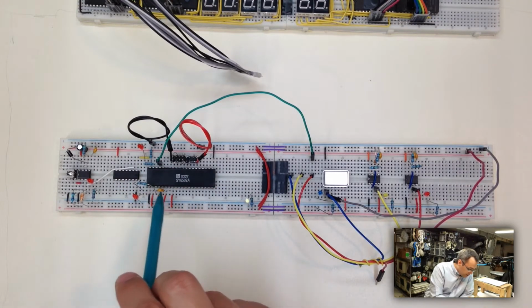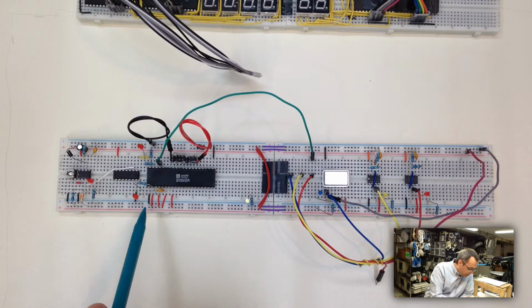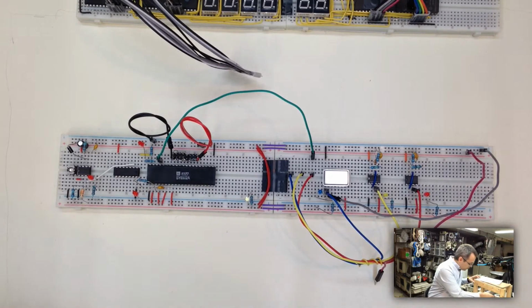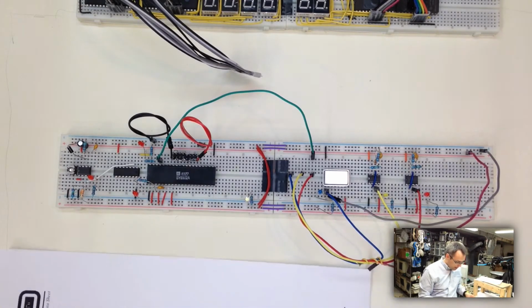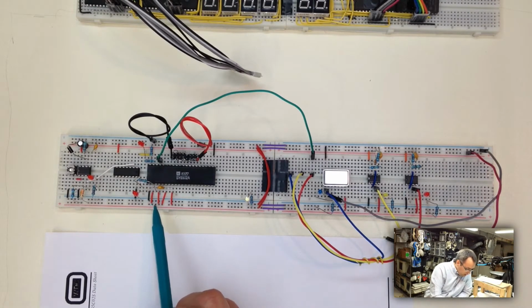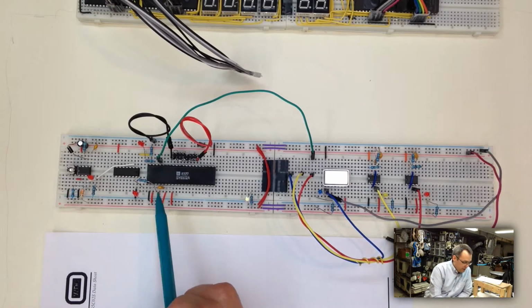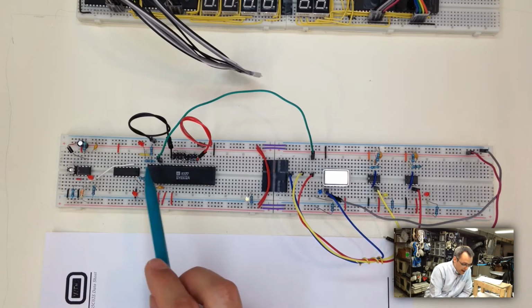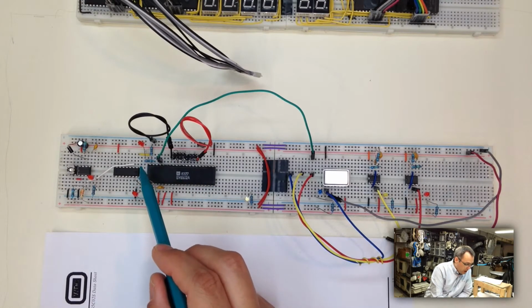Down this side of the processor here, this is our standard power pin. Let me pull out my data sheet so I can remember exactly what we're talking about here. This is the ready pin. We're not using this right now. We may never end up using it. This is our phase 1 pin, which is basically an inversion of the actual clock pin. I have an LED connected to that so that as the CPU receives its clock, it blinks back and forth because it looks neat. I don't really need to have an LED connected to it. I just wanted to.